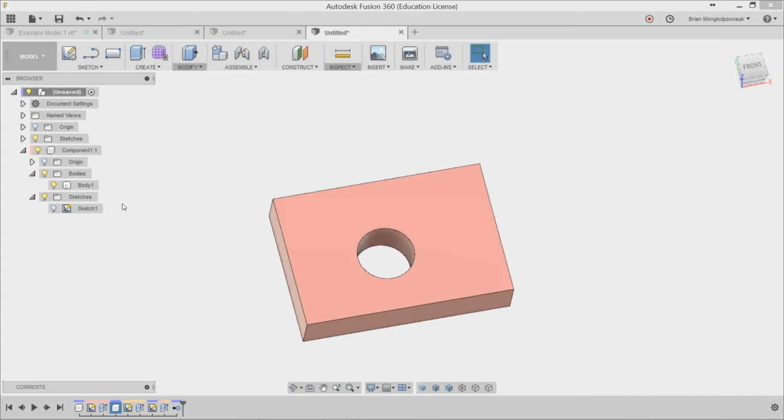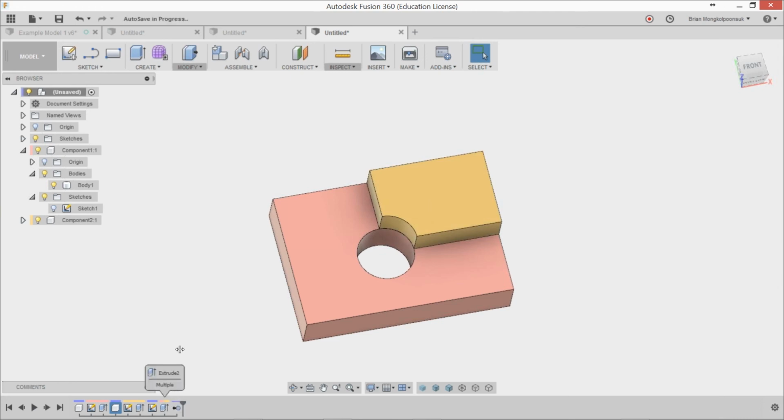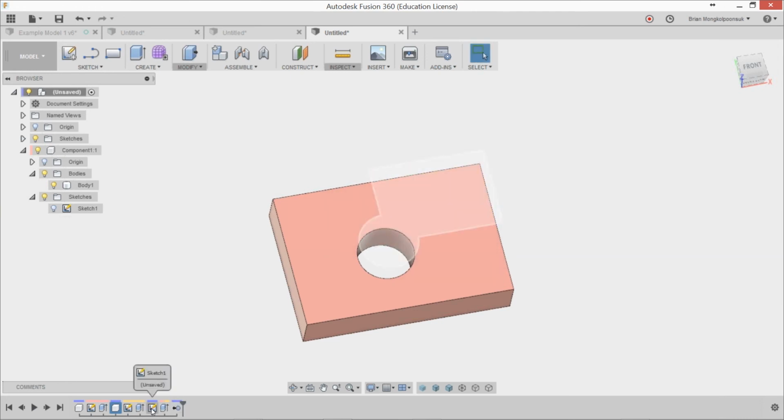What remove does is first, it creates an instance of that in the timeline down below here. So even if you save, exit, and open it up again, you can still have access to that component by putting it back in, dragging this back in the design history. So now you still have that. Also, notice there's no error symbol appearing down below or in the bottom right-hand corner, because the reference is still there. It was just removed. So it's still there in a sense, earlier in time, but it wasn't completely deleted like we did initially.